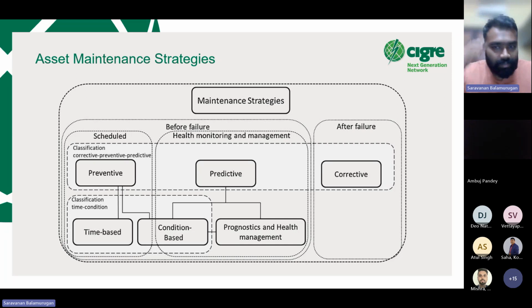So the maintenance strategies, like you can see over here, include time-based maintenance and condition-based maintenance. If you're looking at the maintenance strategies for distribution transformers, right now most utilities have a run-to-fail model, where you just wait till the transformer fails, and once it fails you replace it. But this strategy will not be suitable for something at the generation or the transmission level. So the strategies have to be tailor-made to the location and the usage of the particular transformer. Here you can see the time-based maintenance strategy that gives you preventive maintenance. These are your scheduled tests, the routine tests done at certain time-based intervals.